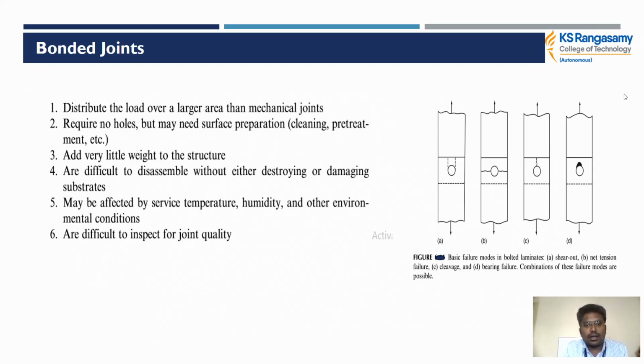Cleaning and pre-treatment are mandatory for the bonded joint. It adds very little weight to the structure compared with the mechanical joint. It is difficult to disassemble without destroying or damaging the parts. The reason is that we use an adhesive, so dismantling is very difficult. It may also be affected by service temperature, humidity and other environmental conditions, and the joint quality is difficult to inspect.